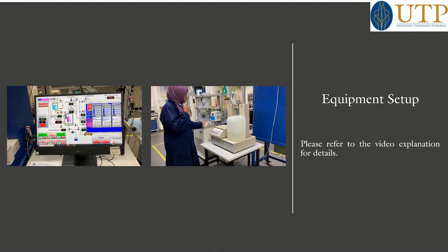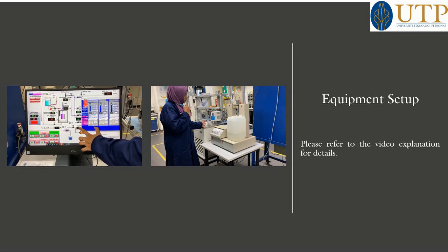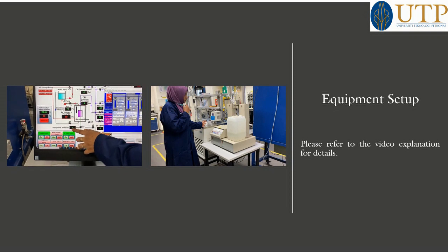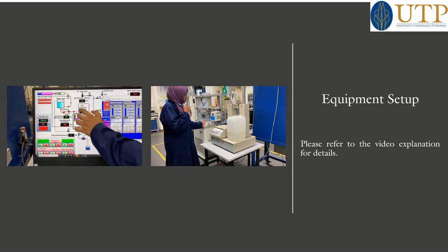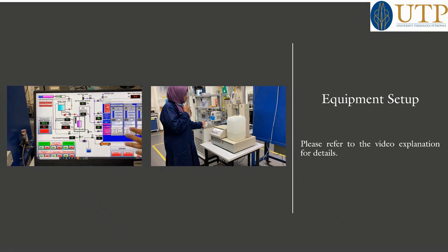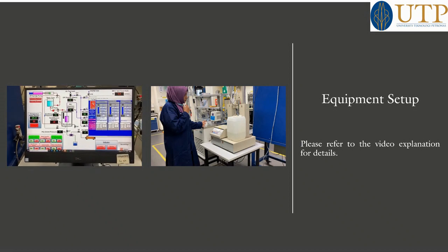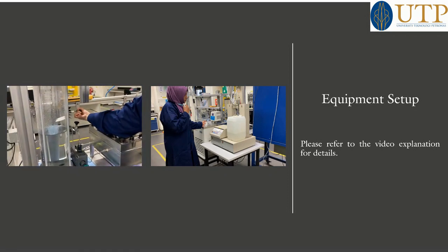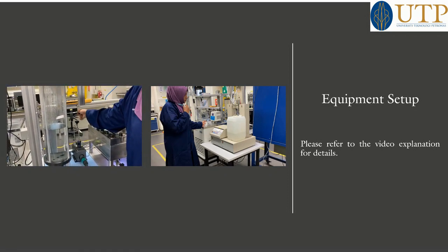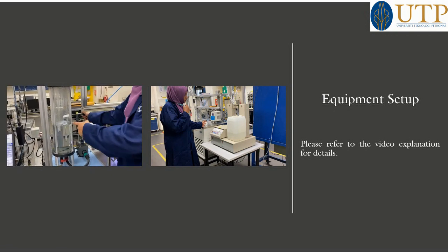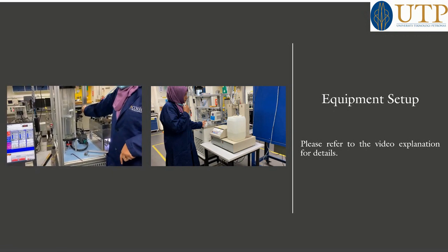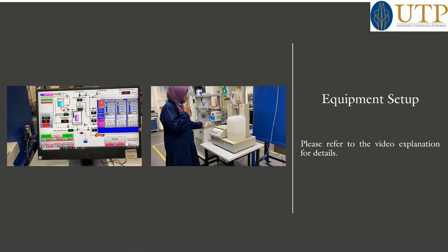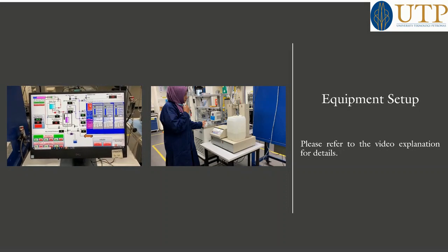Now we can see that BPR is 0. When the BPR decreases, my outlet pressure decreases. When my outlet pressure decreases, my injection pressure and the confining pressure decrease. When we see the confining pressure is nearly 60 to 80, open V6, so that the confining pressure can go back to the water container. Now the confining pressure is only 4.